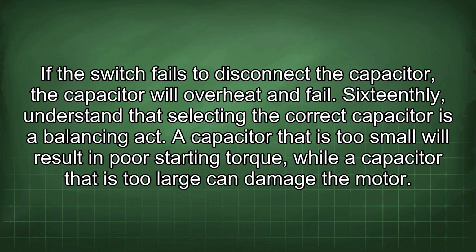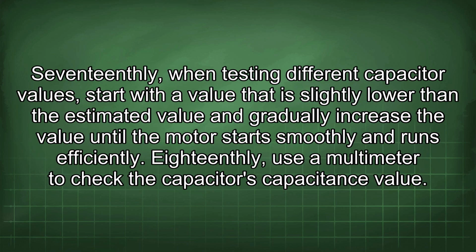16th, understand that selecting the correct capacitor is a balancing act. A capacitor that is too small will result in poor starting torque, while a capacitor that is too large can damage the motor. 17th, when testing different capacitor values, start with a value that is slightly lower than the estimated value and gradually increase the value until the motor starts smoothly and runs efficiently.